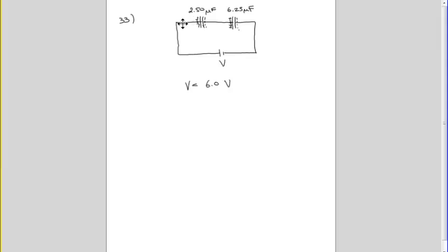What will happen is the electrons will go around here through the battery up to here, and then we get excess electrons. Because we have electrons here, the electrons here will be pushed over to the other plate. So there's no current flowing through the capacitor. It's just shifting electrons from here all the way around, and the ones from here to there create the charges on the capacitors.